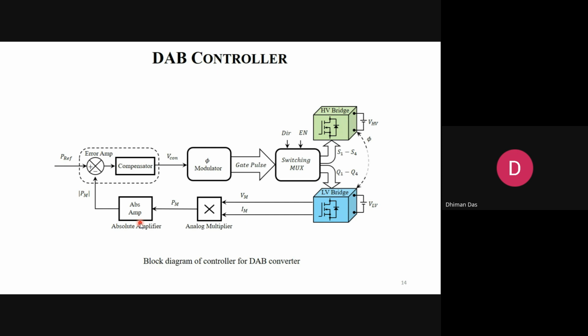So you can have erroneous results or erroneous control, or the control is clipped. For that I need an absolute value amplifier. This is an active amplifier, or active rectification using an op amp. Here you can also operate at high frequency.